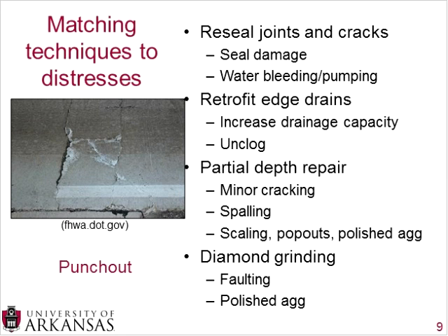So part of any highway agency's preservation technique should include making sure that the edge drains are not clogged. In fact, here in the state of Arkansas, there are 2 crews that work for the Arkansas State Highway Transportation Department, and their only job is to traverse the state roads and make sure that all the edge drains are not clogged, and if they are clogged, to unclog them.